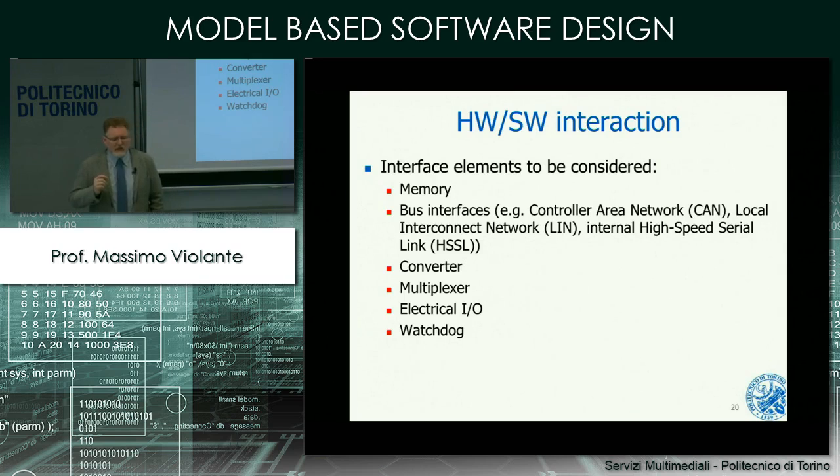Then one of the safety goals that we specified is that we have to be able to provide the service correctly to the driver. And one of the functional safety concepts was that we have to implement a self-test mechanism and inform the driver if something is not working properly. Then how do we do that? For example, if we want to cope with the fault that prevents the microprocessor from running software, we could have monitoring features inserted in our system that are responsible for checking whether the microprocessor is running software or not. We already have seen this when we spoke about the Toyota case, and this is the typical use case for a watchdog.